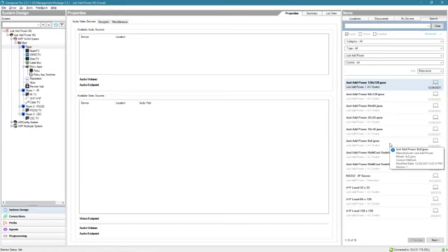You'll notice that there are lots of different sizes of driver. We've got an 8x8 all the way up to a 128 by 128. What these numbers indicate are the number of inputs and outputs available in the driver. So if you have a system that's 8x8 or smaller, you can use the 8x8 driver. If you've got a system that is 8x8 or smaller, you can also use the 128 by 128 driver. Think of the driver size as the maximum size of the system. So you'll have a lot of unused inputs and outputs if you use the 128 by 128, but you have the ability to grow up to 128 by 128.